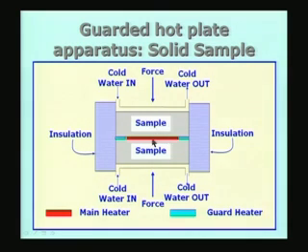And in fact, this figure shows another quantity here, the force. I am applying a force in the direction shown like this, so that the contact between the sample and the hot plate as well as the cold plate is guaranteed, so that the contact resistance will be very small. If there is contact resistance, the temperature we measure will also contain extra resistances due to the contact resistance,